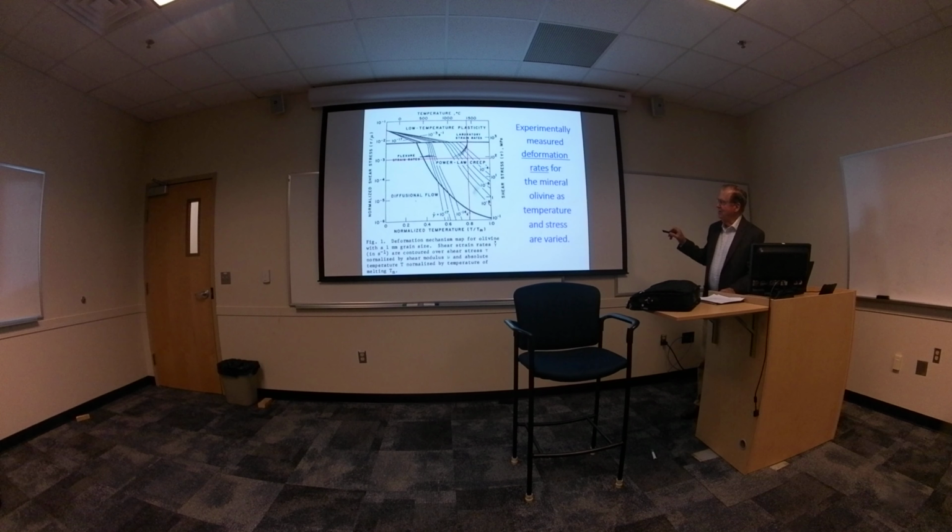And so this is a plot of temperature. Tm is the melting temperature. This is 80% of the melting temperature, and also as a function of stress, both normalized shear stress with respect to the shear modulus, and absolute stress.